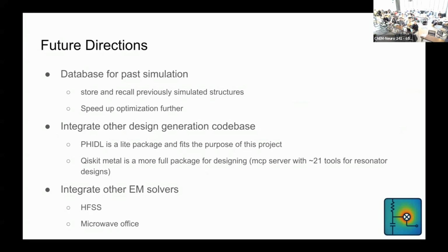One could imagine extending this to support some sort of distributed Butterworth filter. And for that, you would probably want to add analytical calculations that tell you how to construct the transfer function of the Butterworth filter based on, say, functions we already have to estimate capacitance between things. And you will probably need to add some geometry primitives that give the LLM some insight into how to lay out the Butterworth filter. Does anyone else have stuff to add?